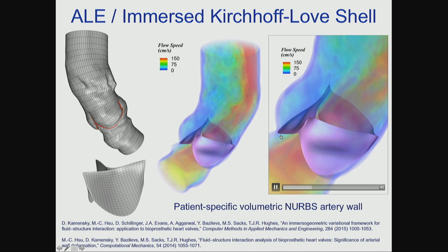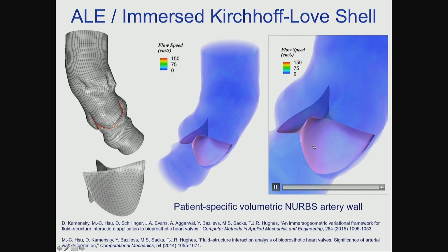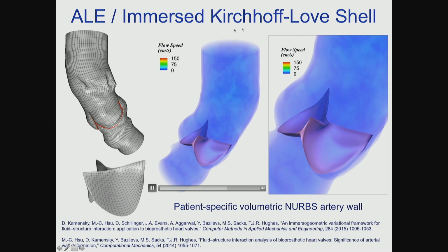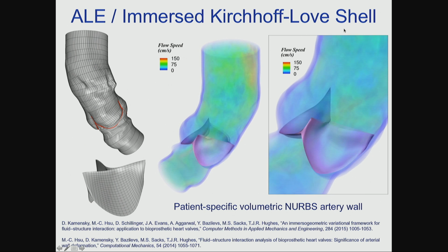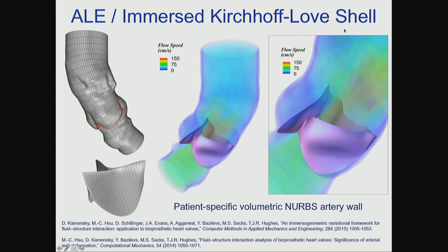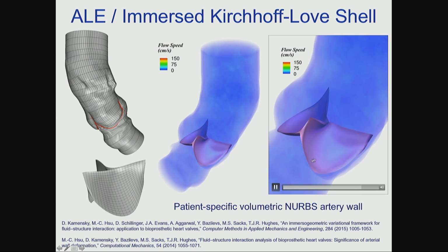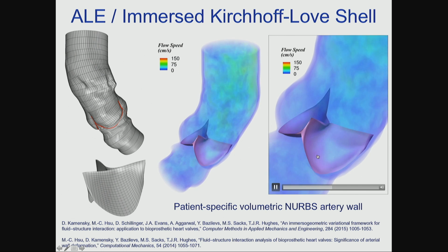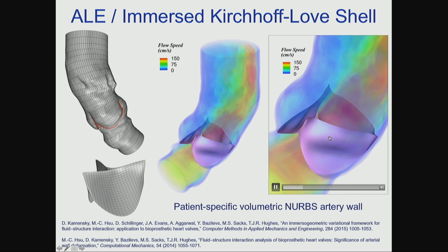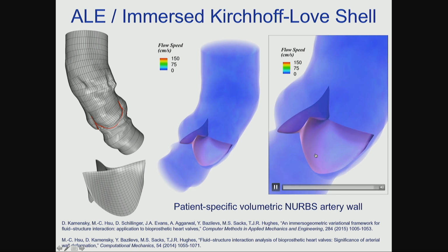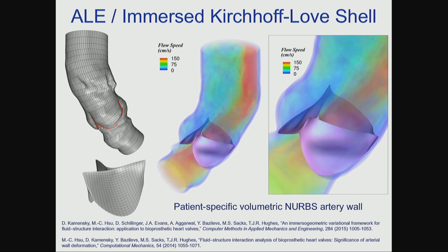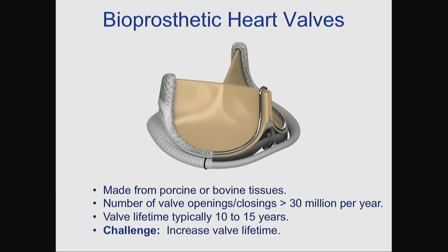And then the leaflets of the aortic valve are modeled with Kirchhoff-Love shell elements. Again, rotation-free shell elements. You don't need rotations because you have smooth basis functions. And you can see that there's a lot of technology here because you have this shell immersed, moving through a moving background mesh. Now, the design application here is actually to bioprosthetic heart valves.